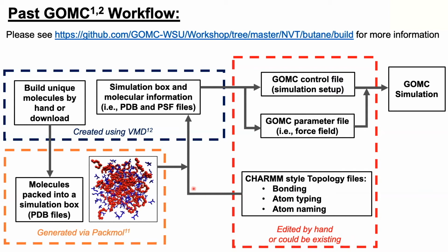And then you combine these files using VMD, and then you come up with a simulation box that is now a PDB and a PSF, which means it has the coordinates from the PDB and the bonding information, all the bonding angles, dihedrals, and impropers from the PSF file. And to get to here, you have to write another script or modify an existing script at least.